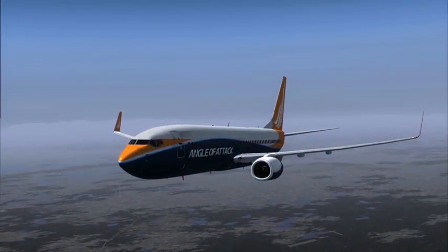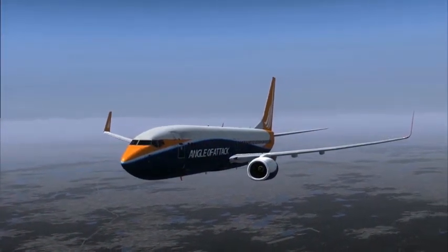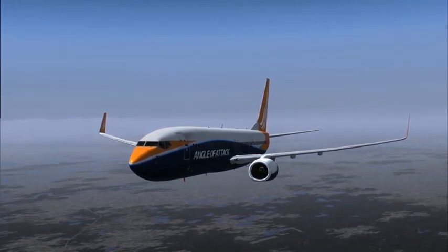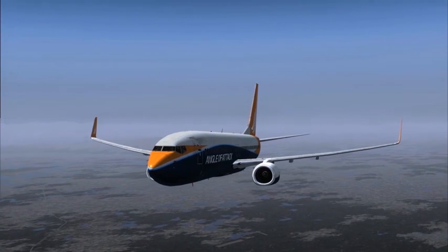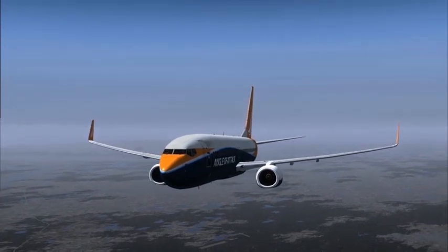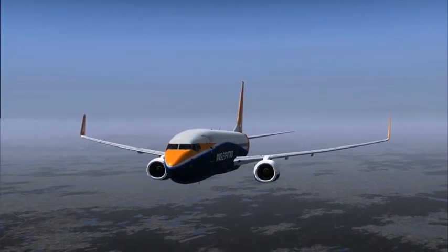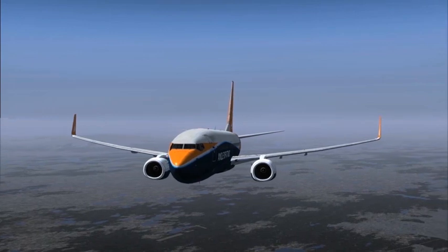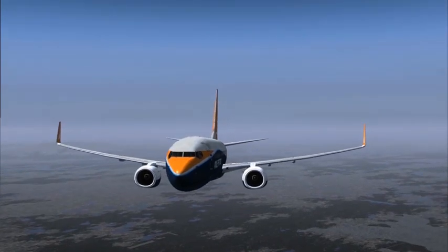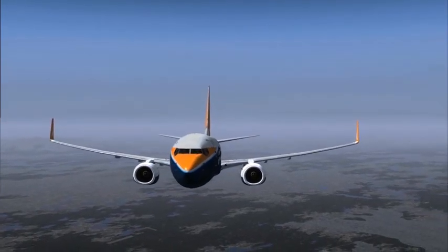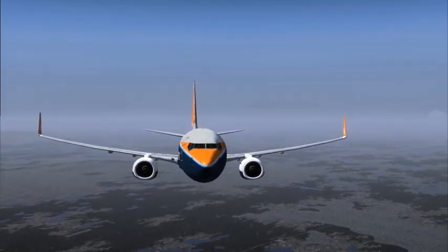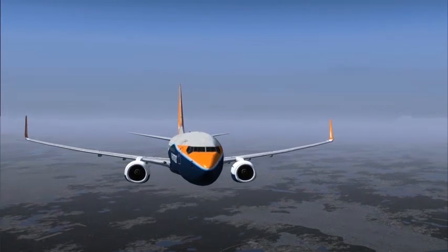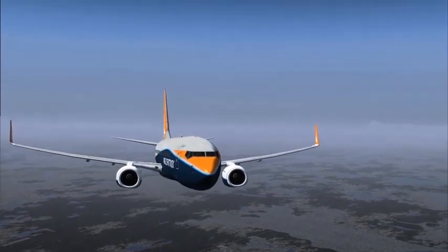Moving on. In order to maintain a comfortable amount of air and oxygen for the passengers and crew, the pressurization system pressurizes the cabin to a safe altitude. The bleed air system and air conditioning packs introduce air into the cabin. But a cabin pressure control system is in charge of controlling the rate at which air flows out of the cabin by closing and opening a valve in the aft fuselage, known as the outflow valve.